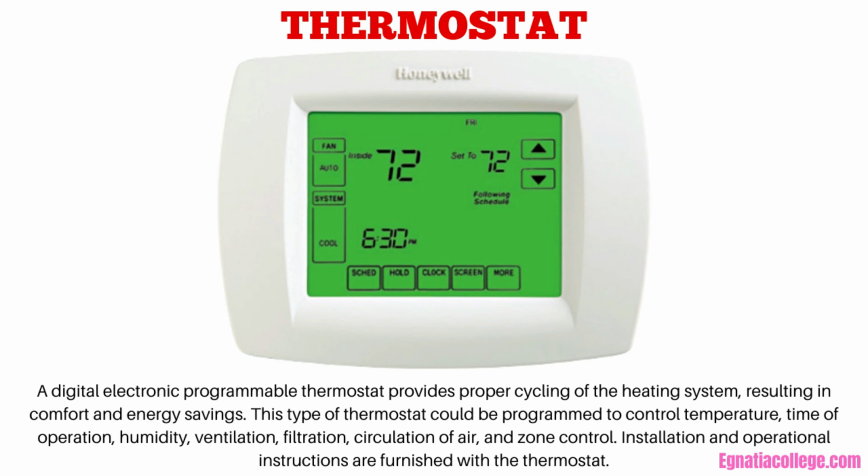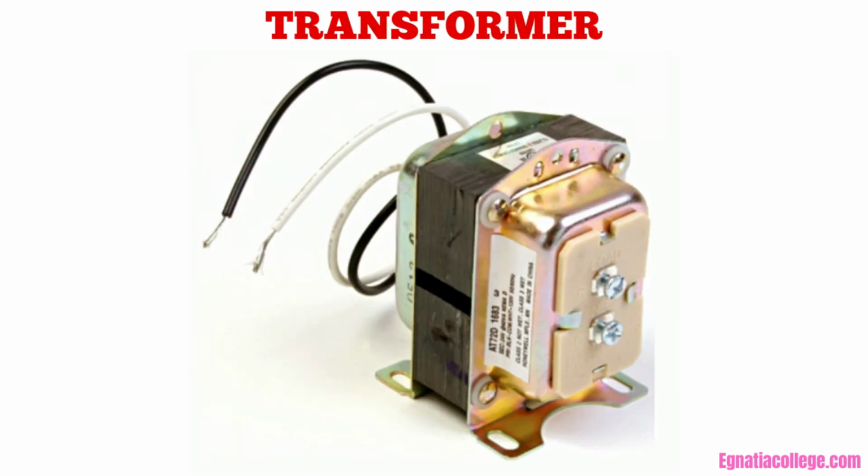Some thermostats contain a small vial of mercury that tips. So the mercury closes the circuit by bridging the gap between the electrical contacts inside the vial. These thermostats must be kept perfectly level to ensure accuracy. Warning: do not throw mercury thermostats into the trash. Mercury is a hazardous waste material and must be given to a waste management organization for proper disposal.